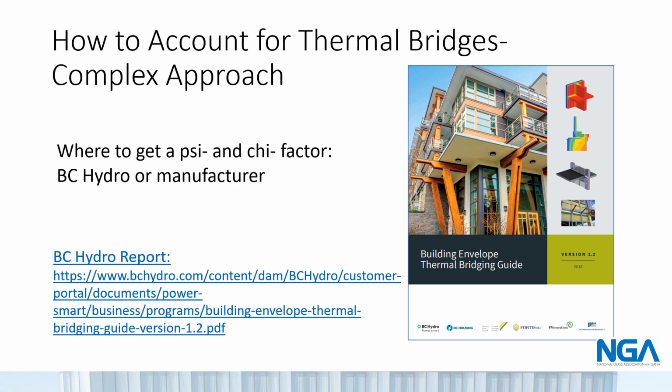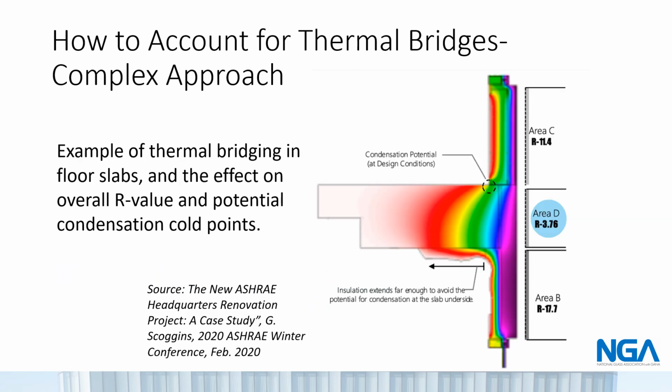Data may also be used to determine if the interface should be thermally enhanced to meet whole building energy objectives. The design team may use the data to determine if the enhancements are cost-effective compared to the anticipated energy savings. Modeling can also provide useful information about surface temperatures to help locate cold points below the dew point at different design conditions, and therefore help identify potential condensation areas.